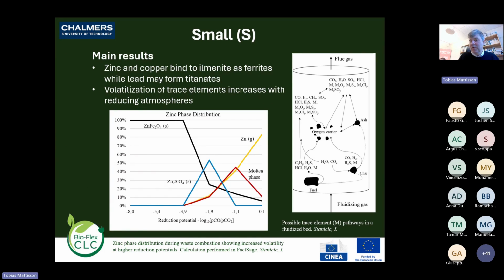lead we have done. This has been related, again, to waste fuels, perhaps not biomass, but municipal solid waste or RDF can contain trace elements and corrosive elements which are not very good. And given that you are replacing sand in normal fluidized bed systems with oxygen carriers, you can have different types of chemical processes than you would have in normal fluidized beds.